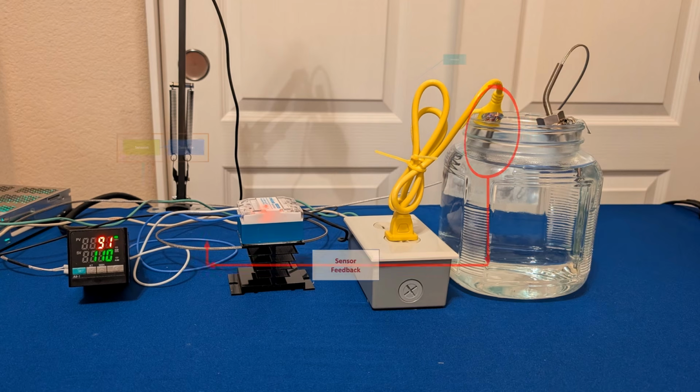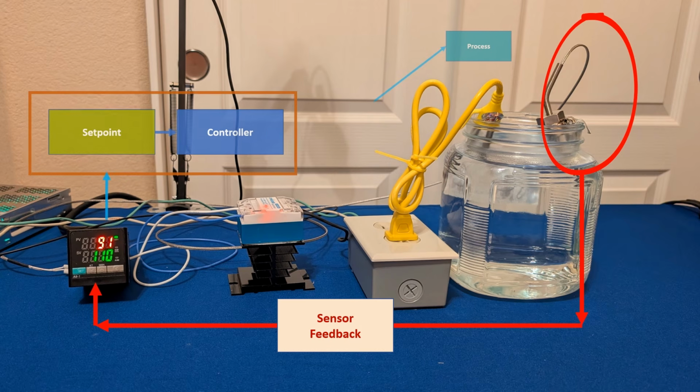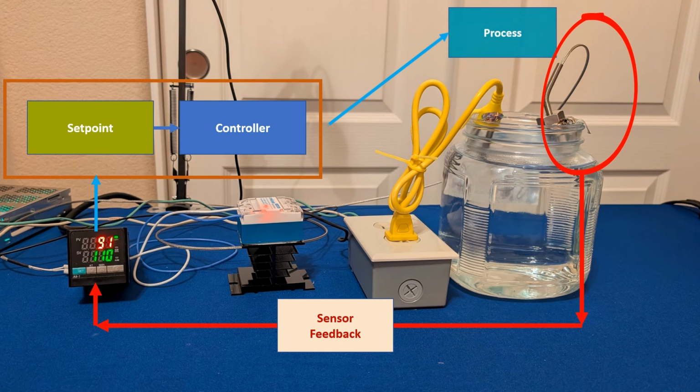In our setup, we're heating water. A thermocouple measures the water temperature and sends that signal to the PID controller. The controller compares the measured temperature to the set point. If the temperature is below the set point, the controller turns the relay on, which energizes the heating element and starts heating the water. As the temperature gets closer to the set point, the controller adjusts the heater operation to keep the temperature stable. The thermocouple then measures the temperature again and sends the new value back to the controller.